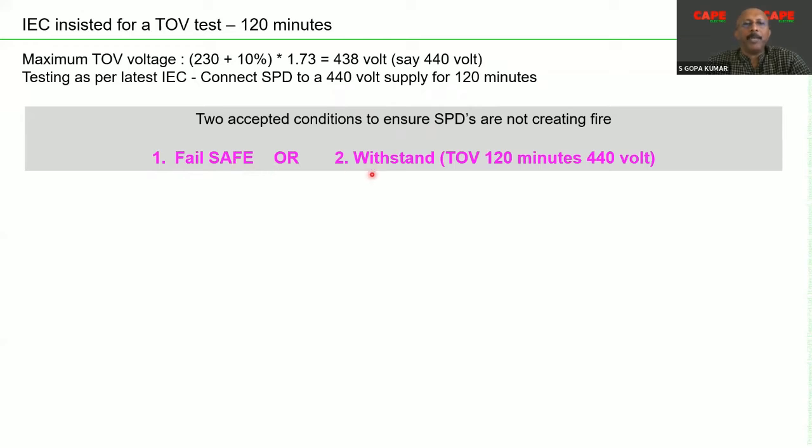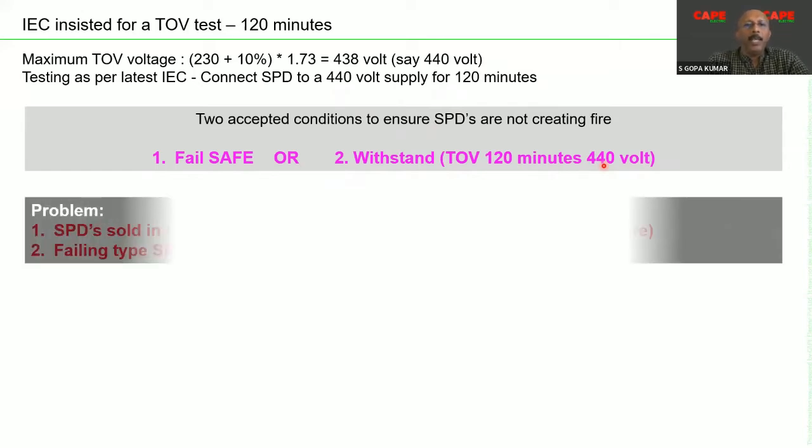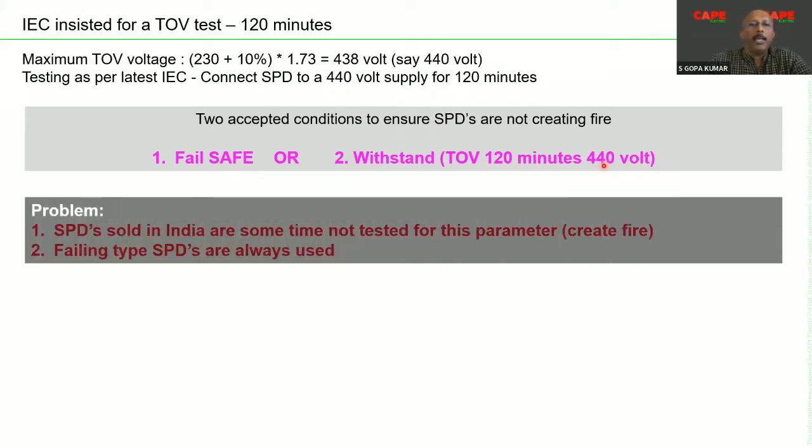Safe fail is accepted. The second condition, the SPD may withstand this 120 minutes at 440 volt. These two conditions are accepted. SPDs which are blasting or catching fire are not suitable to sell in the market. These tests have been included and recommended in the standard, but as we always know, in India, such new techniques are introduced quite late in the market, probably after 10-15 years.